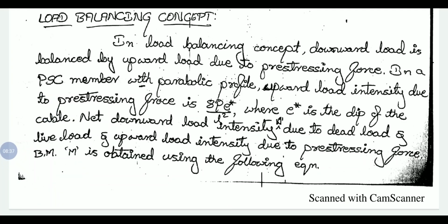Next concept, and it is a more important concept: the load balancing concept. In this concept, the name itself indicates we are balancing the load. As we know, prestressing force leads to upward deflection of the member, and dead load and live load lead to downward deflection of the member.